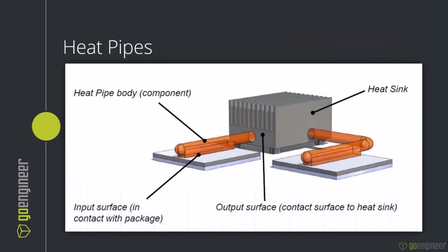Doing that simplifies that really complex process down to just a simple solid, and then SolidWorks uses empirical and theoretical formulae to calculate the heat transferred through this body. So it saves a ton of time versus trying to capture that data. And as you probably know, SolidWorks Flow can't even capture that phase change, so this would be something you can't do unless you have access to these heat pipe tools.